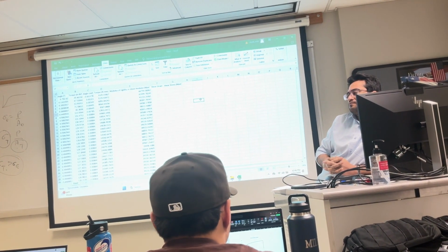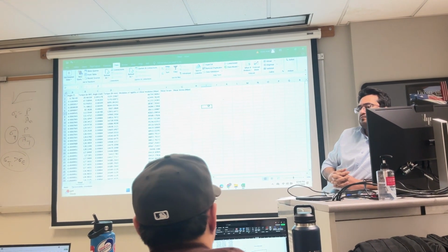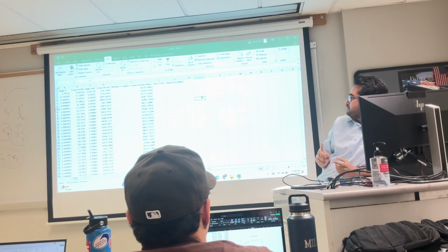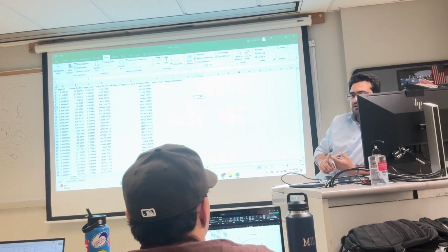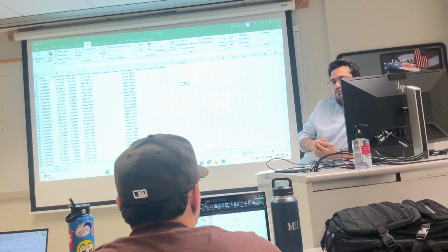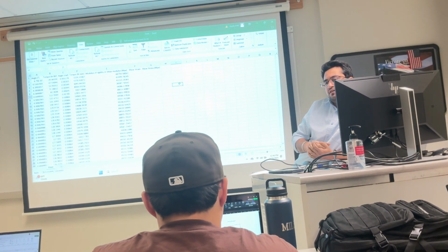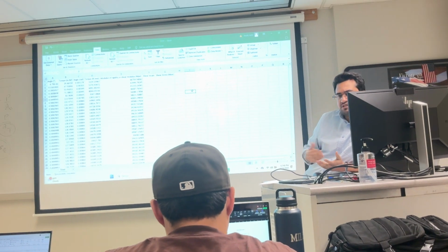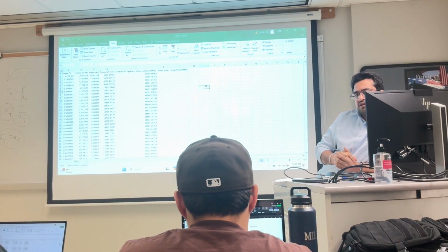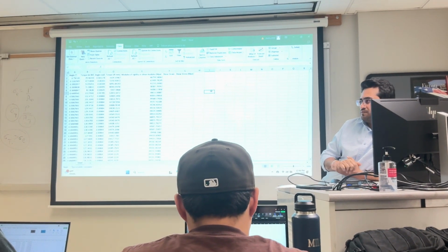Okay, yeah. Stress strain guide, and you said you wanted the max for rigidity, strain, and stress? Yeah, for the rigidity, you have to select certain data from the plot. That will give you the rigidity. Then maximum stress, maximum shear strain, and shear toughness.